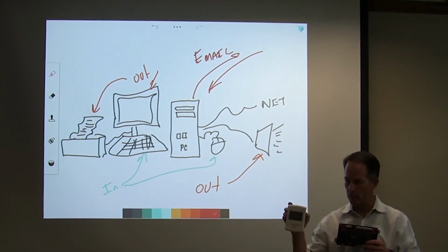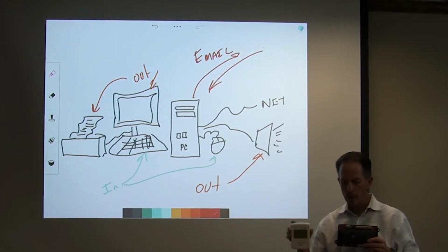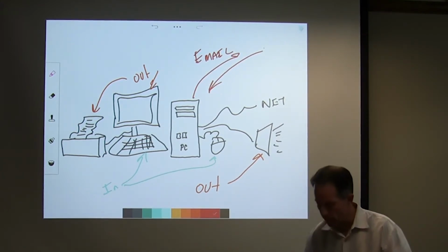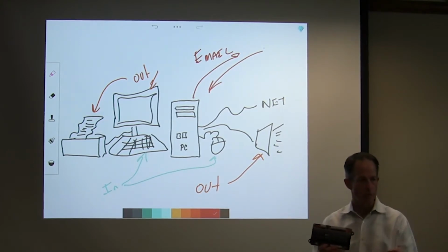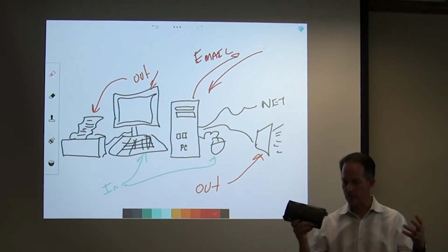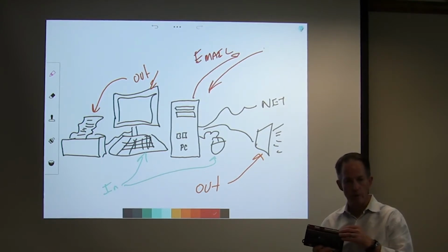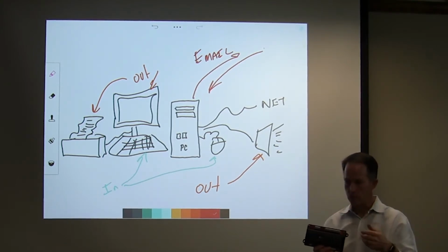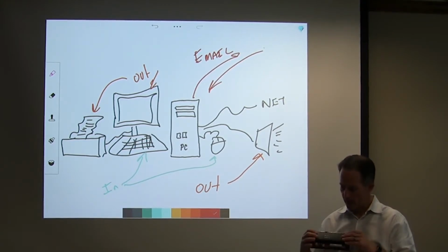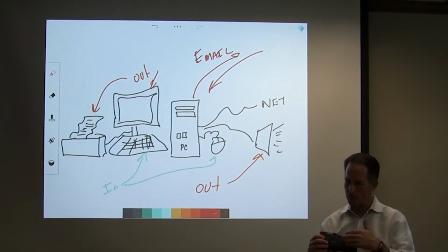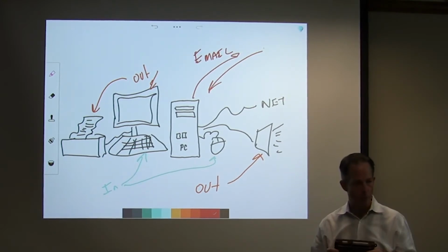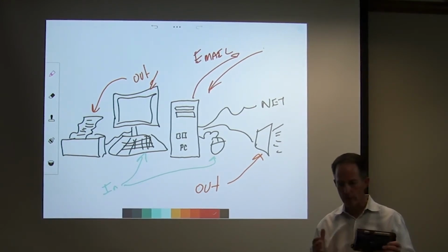Now, this is also a Delta stat, and these are a simpler type of application, so they're more configurable. And so we do have a little bit of both, but when we get into mechanical systems or heat exchanger rooms, any type of fans, things like that, we're going to probably be using controllers that are more like this because they're flexible. They have universal inputs, which I mentioned earlier, where these inputs can be 4 to 20, 0 to 10, 0 to 5, resistive, or just on-off. And then our outputs can be set up, and they can be programmed with whatever sequence we want to do. Okay, so we have those kinds of options.